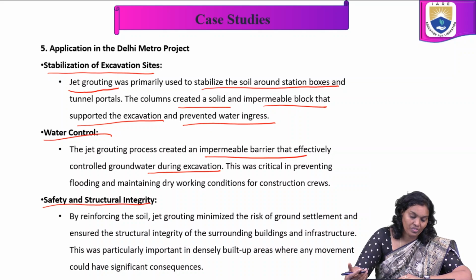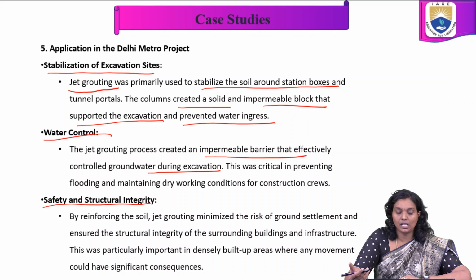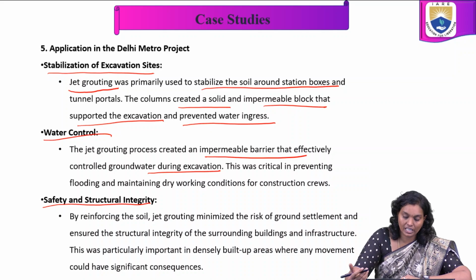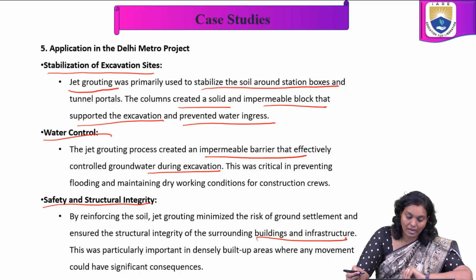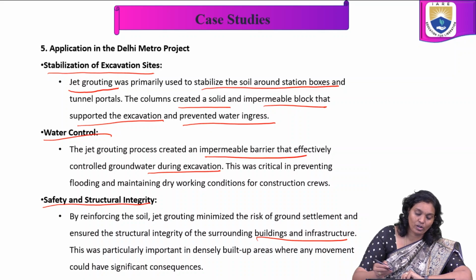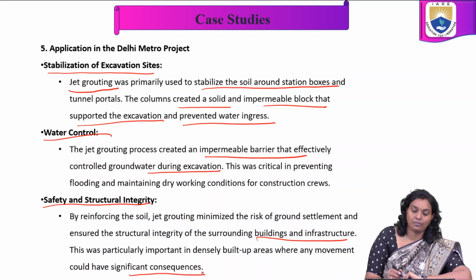And also, this is important in safety and structural integrity. By reinforcing the soil, the jet grouting minimized the risk of ground settlement and ensured the structural integrity of the surrounding buildings and infrastructure. This was particularly important in densely built up areas, where any movement could have significant consequences.